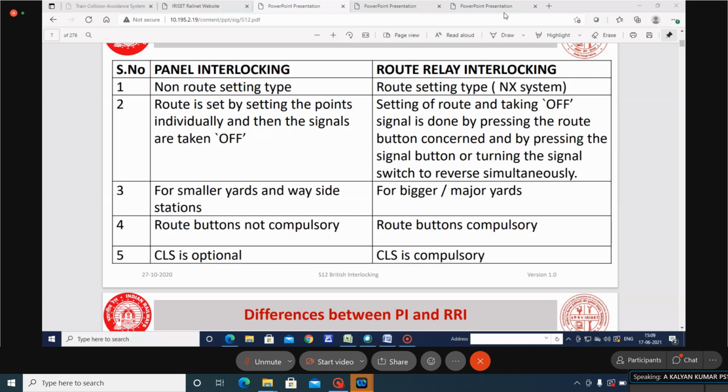Okay, now the crank handle should be in. What is that? Yes, crank handle should be in. Since the point can be operated by mechanical means also, while operating by one means, we are not permitting the other means to operate. So when I am going to send the power, I ensure that the concerned crank handle for that particular point is in locked condition. Yes, if these three conditions are satisfied, can we operate the point?